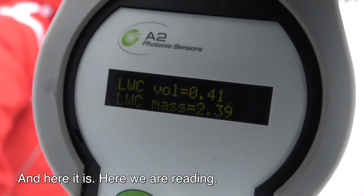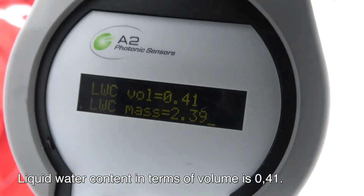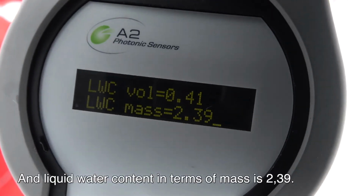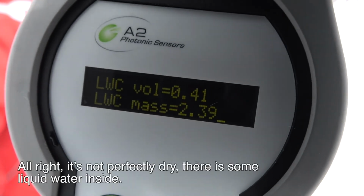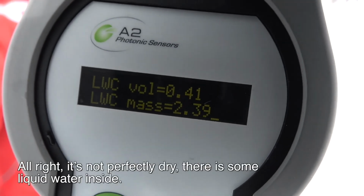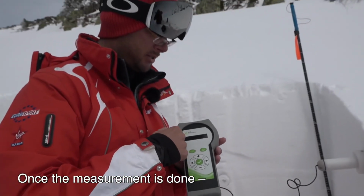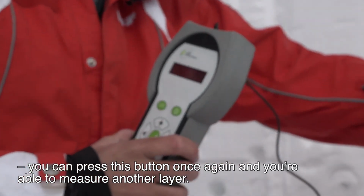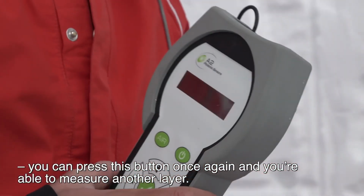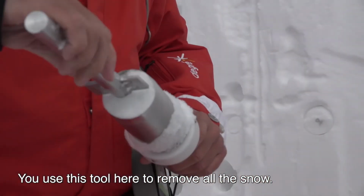I press OK once again, and here it is. So here we are reading liquid water content in terms of volume is 0.41, and liquid water content in terms of mass is 2.39. All right, so it's not perfectly dry. There is some liquid water inside. Once the measurement is done, you can press this button once again, and you're able to measure another layer. So you use this tool here to remove all the snow.